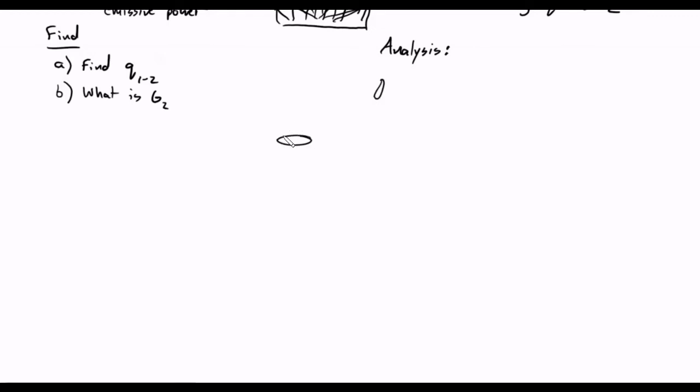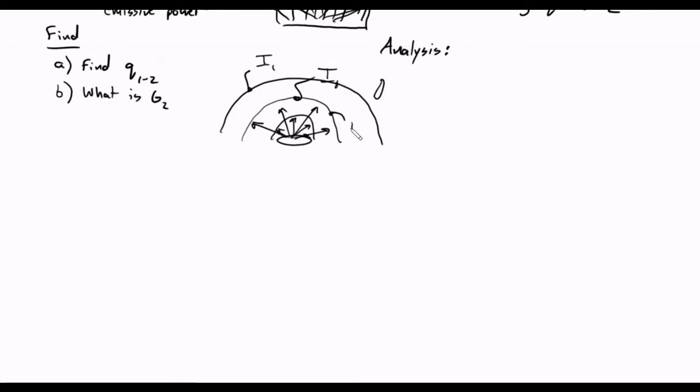So when we compute the intensity of surface 1, that intensity is uniform in all directions for surface 1. Which means as the energy goes outwards, what remains constant is the intensity. At any point, the intensity remains the same. The intensity of surface 1 stays the same. It's almost like an intensity field, kind of this constant propagating through the hemisphere, so that once we hit surface 2, we know how much intensity is there, and from that we can find the heat rate.